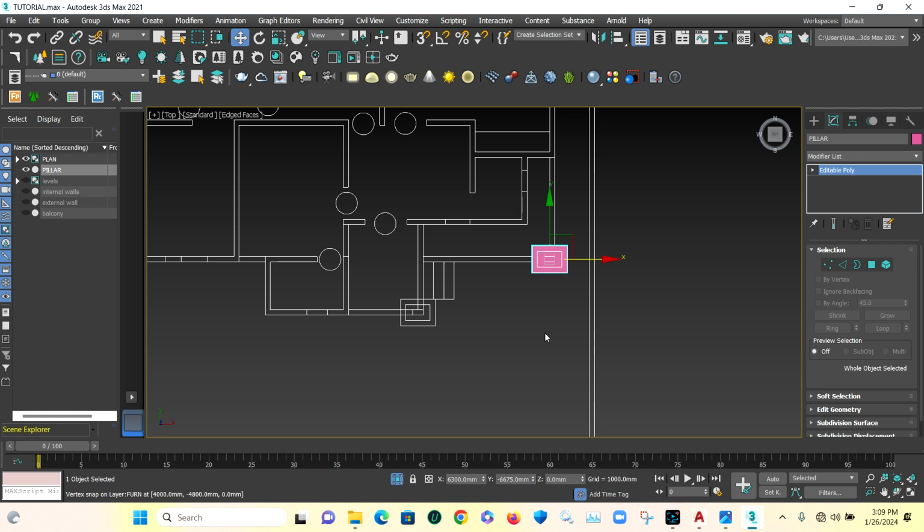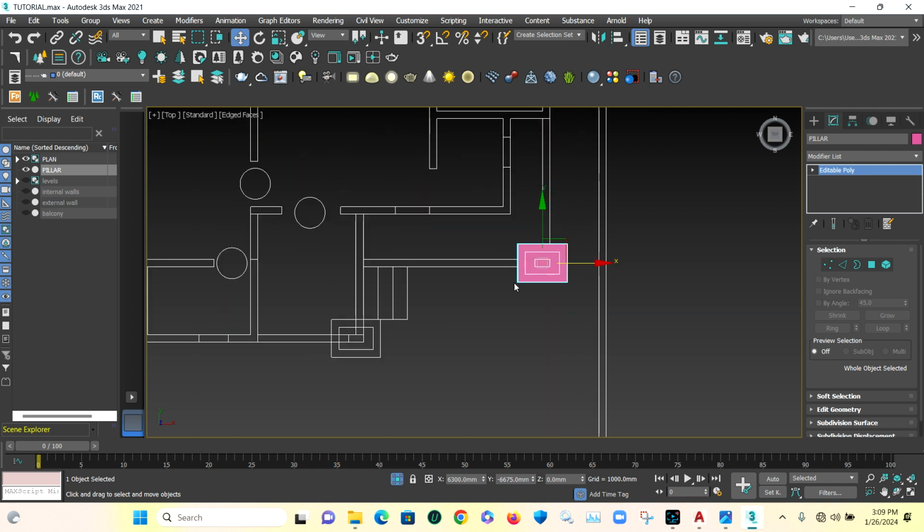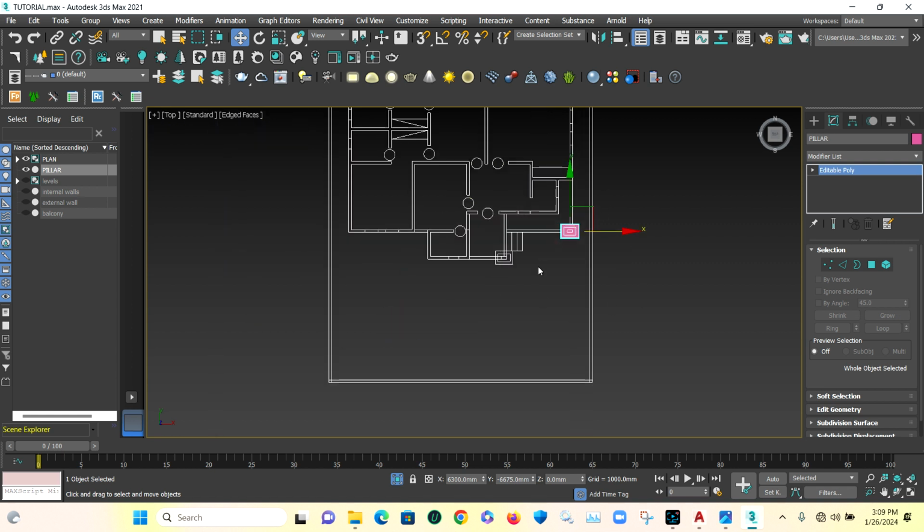You know, first I've talked about the move command. Now let me do it again. Before you move, the first thing you do is you introduce the movement pattern, like the axis you want to move on, whether you want to move on X axis or on Y axis. Now if you want to copy, I already showed you. Once you want to copy, just hold the shift and then implement the move command. You copy. Now let's copy this. Let's copy this now in any direction at all. Just want to copy it and place it here. Now let's copy first.